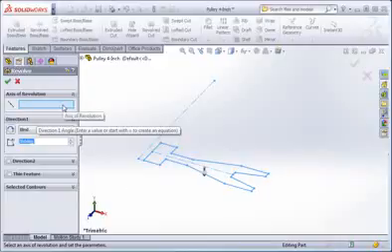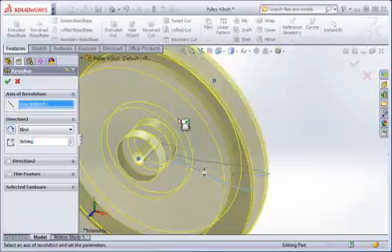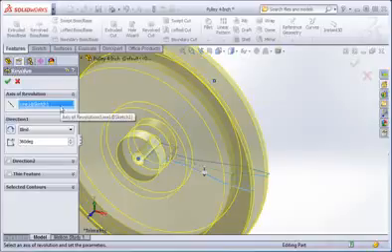The axis of revolution window is highlighted in the Property Manager, so the next step is to select the axis of revolution, which is the vertical construction line. Click the line, and the preview of the operation appears in the graphics area. If you look in the axis of revolution window, you can see that line 1 that was drawn in sketch 1 is the axis of revolution. If you recall, the first line drawn in the sketch was the vertical construction line, so this line is line 1, and it was drawn in sketch 1.